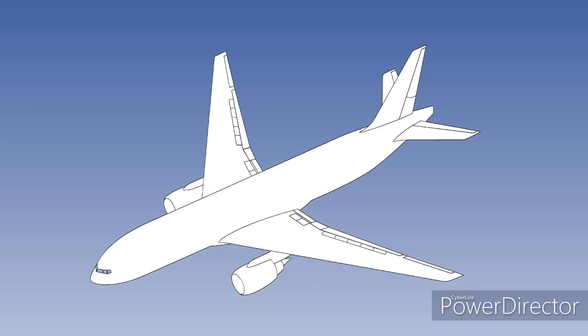To summarize, power flying controls must be used on large and/or fast transport aircraft that have control forces too high for the average pilot. Power-assisted controls retain some of the control's natural feel, but most of the force required is provided hydraulically. Fully powered controls use hydraulics to provide all the force needed to move the control surfaces into the airflow, but there is no direct link between the pilot's controls and control surfaces, and therefore an artificial feel system is required to give the pilot the stick force necessary to fly the aircraft safely.